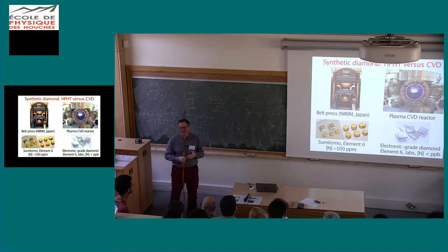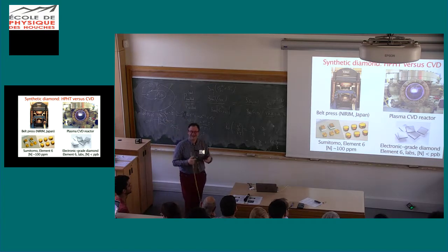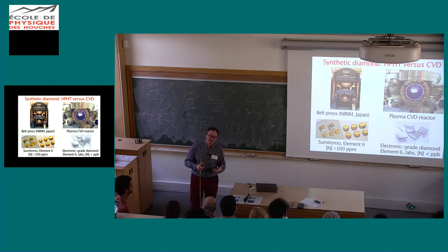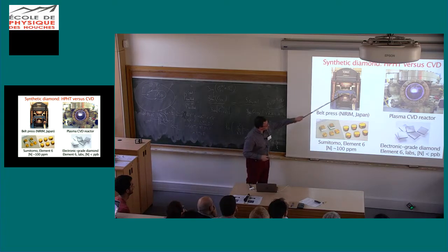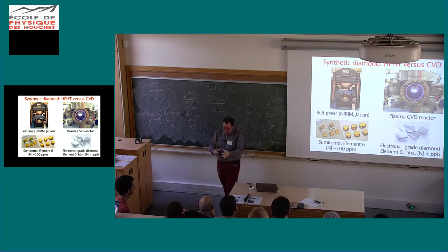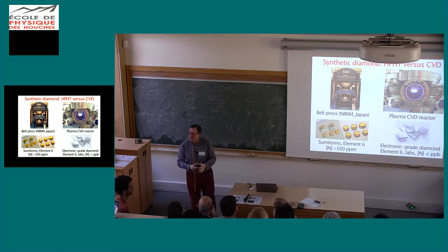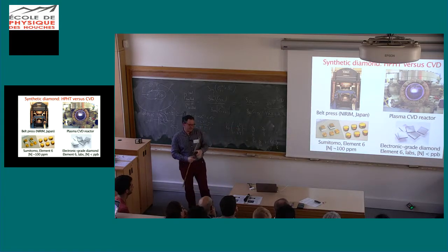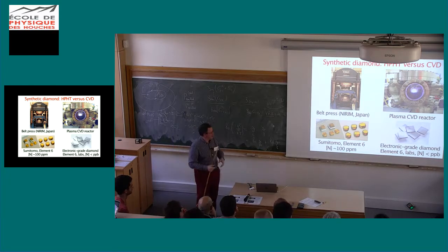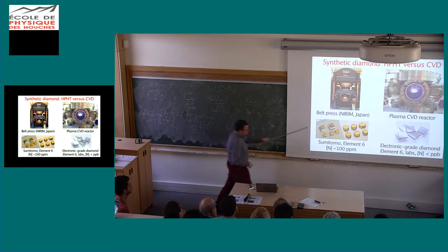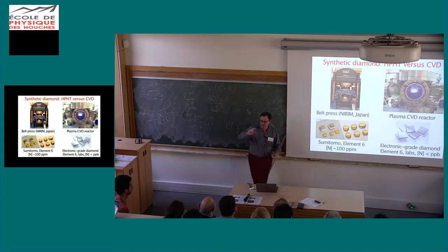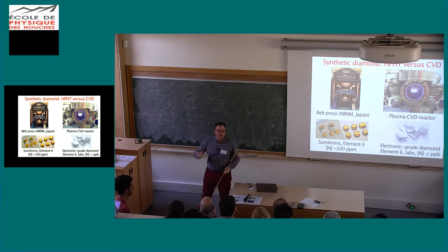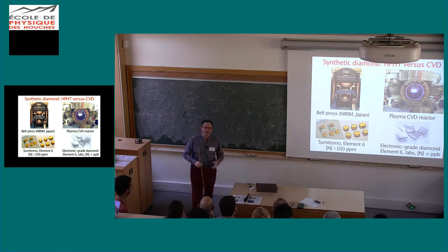It's a kind of egg and chicken problem, because this is homoepitaxial growth, so you need to start with a diamond which is already a single crystal. So for instance, you will make those crystals here, and these could be quite large, almost 1 centimeter in dimension can be produced. And once you have that, then you will deposit on top of that non-pure diamond the layer of ultra-pure diamond, which can also be doped, for instance, for high-power electronics.